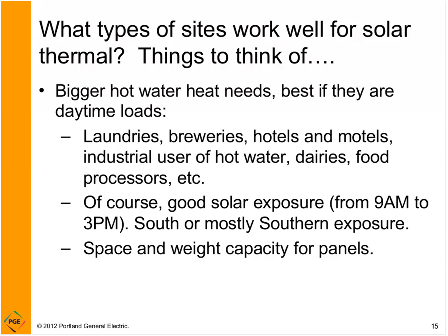Lastly, I need to mention that there are structural concerns when you start putting solar thermal panels on your roof. You have to be considerate of the weight of these panels. With the water in the panels, they can get fairly heavy on a loading per square foot or pounds per square foot basis. We've found that a lot of recent construction has a fairly tight tolerance for loading. In other words, when they built the building, they built it just to code and didn't use anything beefier than they have to for roof support. So you'll need to get your structural engineer involved at some point to verify that your roof has the capacity to hold these panels up.